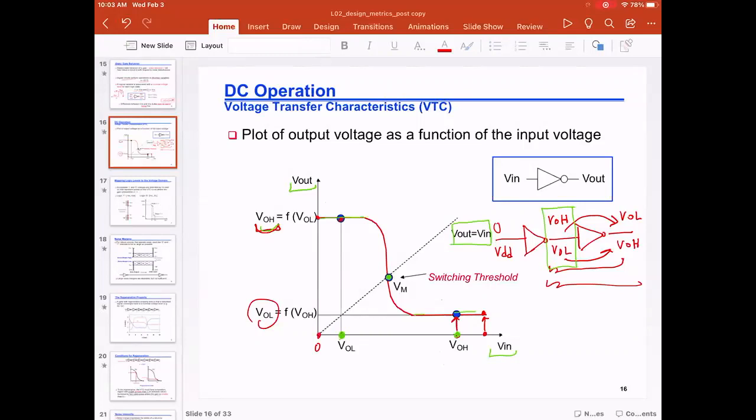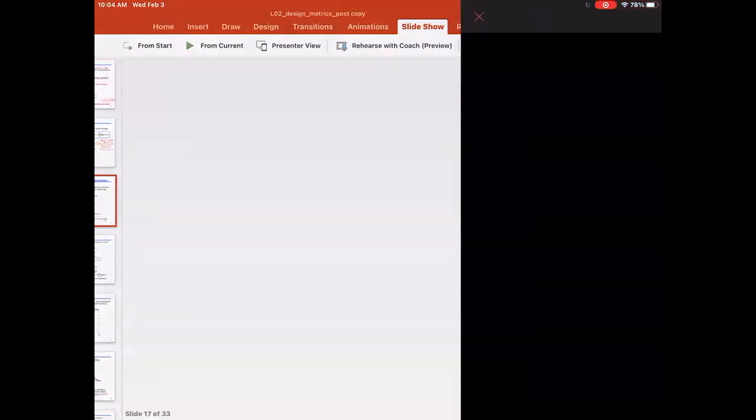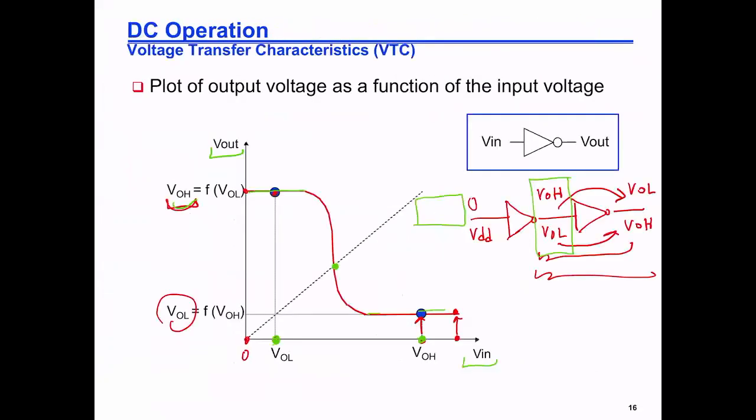resistor that is being used or the minimum area that I can operate with. So for a given design, therefore, we define the metrics, and those metrics that we look for are typically VOL and VOH. So we said that if I have a chain of two inverters operating within the circuit, if I input 0, I will get the output being high, VOH, and if I input VDD, I will get the output being low, which is VOL, okay?